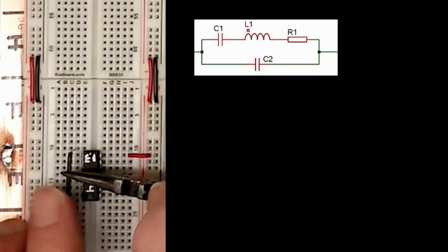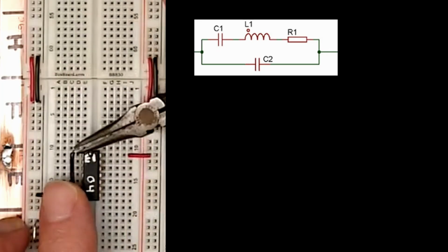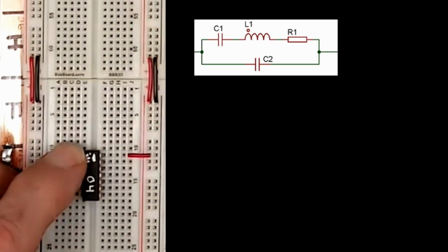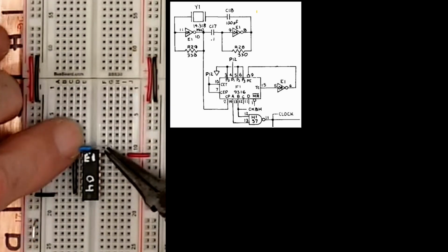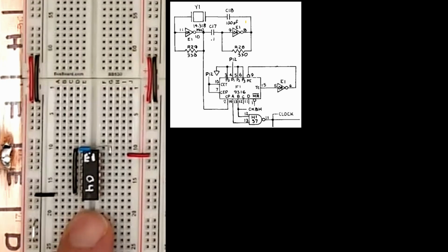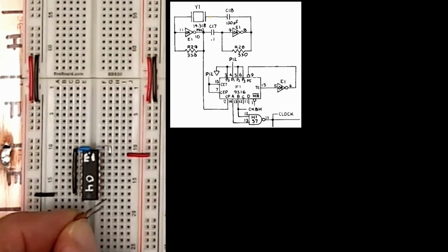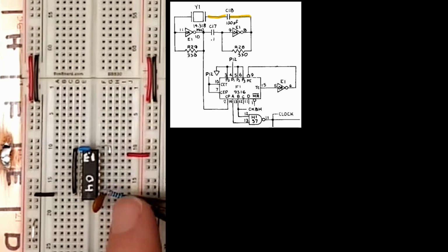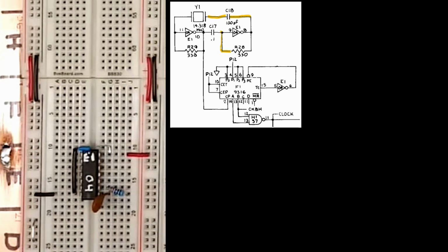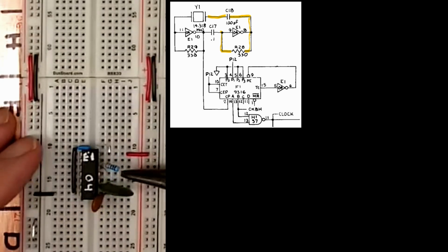In theory, the crystal is an RCL network fighting between charge storage and discharge at a resonant frequency. It also abuses the linear region of the bipolar inverters to amplify the changes, so I'm not sure if this design would work in CMOS. I'm too lazy to try it, someone let me know. Most crystals are parallel resonant, so this happy little cap here just assures there's enough series capacitance to start and maintain oscillations, and many designs don't have it.